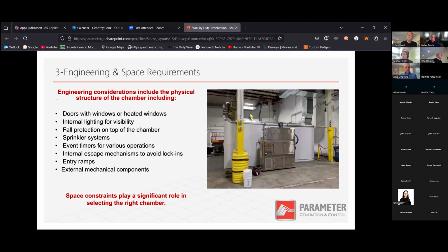But again, even if you are within that range, if you swing from 65 degrees to 95 degrees in a 30-minute time period, you will see a small swing of the performance inside the room. The humidity is less concerning when it comes to ambient because the rooms are generally vapor sealed. So the room on the side that you see has silicone in the seams, and the entire system is vapor sealed in its own environment. So it's really just the temperature swings in your ambient environment.